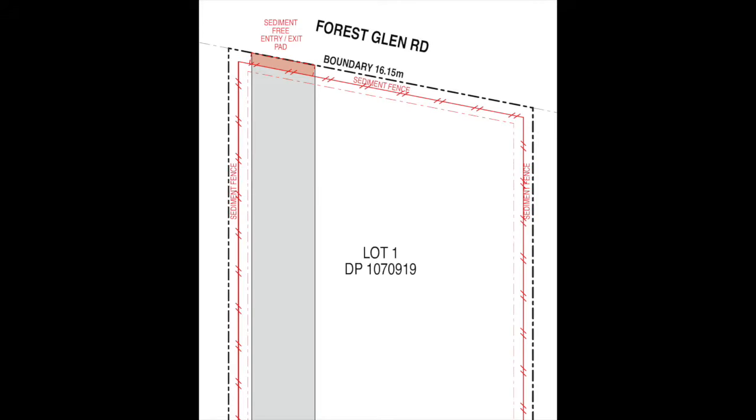We may also use the site plan to represent the sediment and erosion control requirements, showing where we're going to have sediment fences or gates or barriers in order to preserve the natural environment during construction, so that we don't have sediment washing across the site into neighbouring properties or maybe into nature reserves.